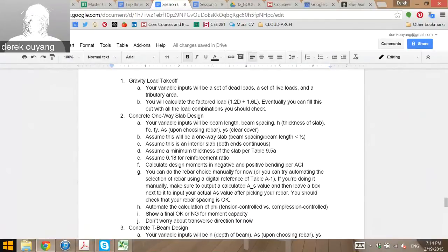And the other way to think about this is a lot of the charts you might have seen in concrete or in steel, where you've got, let's say, the one we're going to try to build today together. You have rho on the x-axis. You have M, your moment capacity, normalized to BD squared. And then this chart is for a given Fy of steel, let's say 60 ksi.